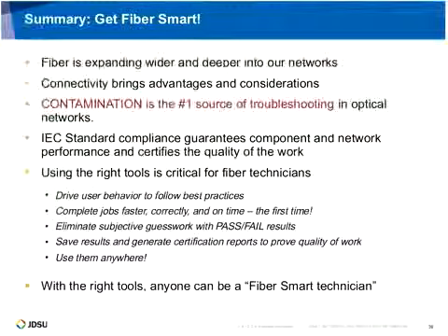The first question: IEC 61300-3-35 seems to be the current standard that defines the common set of requirements for interface quality. Is it so, or are there other standards? Hopefully this was addressed a little at the beginning of the presentation, where I talked about 568C adopting the IEC standard. That's actually true for most situations. Other organizations are looking to the IEC standard. They were the first one.